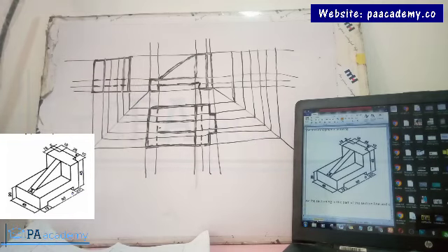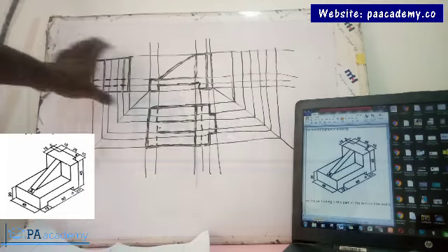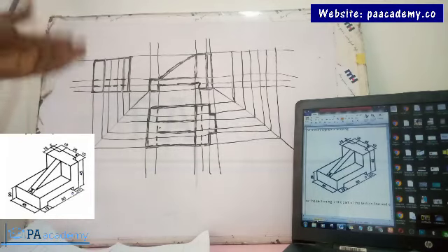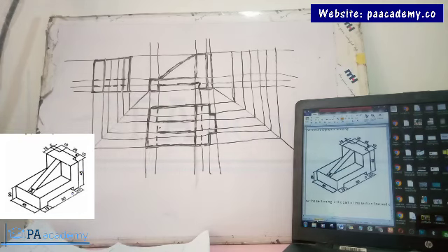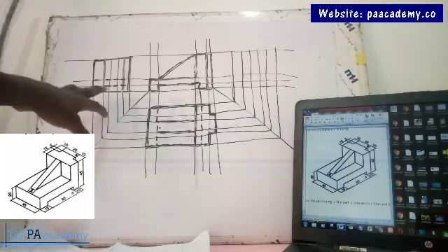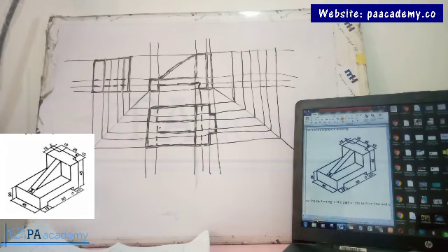Just like what I said earlier, if all your projections are correct, whenever you are drawing the side view, you don't really need to introduce any new lines. It's the projections that you have done that you are going to use to complete it. All right, so that's another hidden detail. Don't forget what short dashes mean in engineering or technical drawing. They are used to indicate hidden details. All right, so there's another hidden detail we also need to show.